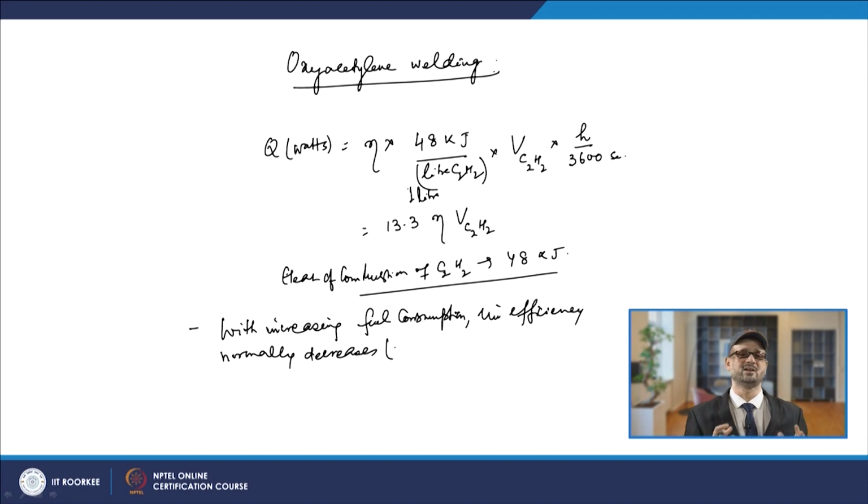If you increase the fuel amount more than what is required for complete combustion, there will not be complete combustion taking place, and in those cases there will be loss of fuel, and that will decrease the efficiency. So because of incomplete combustion, your efficiency will be changing.